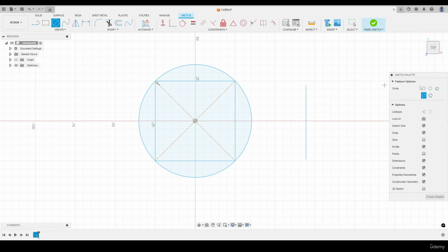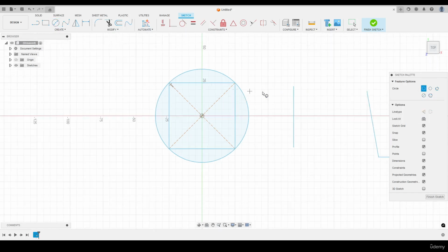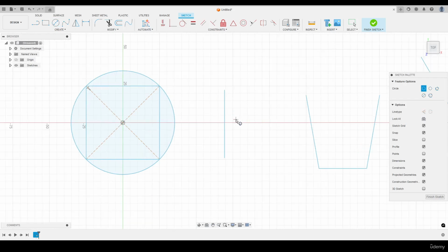The next tool we're going to take a look at is the 2-point circle. So if we come over to our box and select the 2-point circle, just zoom out, pan over a bit. The 2-point circle, the very first point we define is a place on the circumference of the circle. If I left click at the end point of this line here, that's one position of my circumference, and then you'll see the next click, wherever that may be, will be the other circumference. So that will define the diameter. So in this case, I could snap onto existing geometries, or I could just input a diameter. In this case, I'm just going to snap on to the midpoint of this line here. I'll left click there, and there we have our 2-point circle.